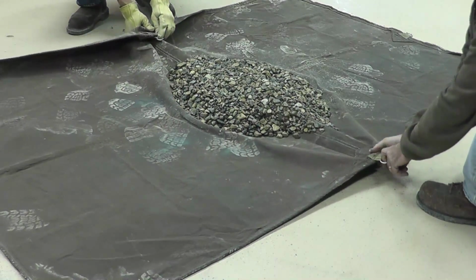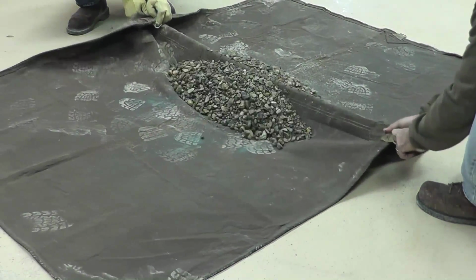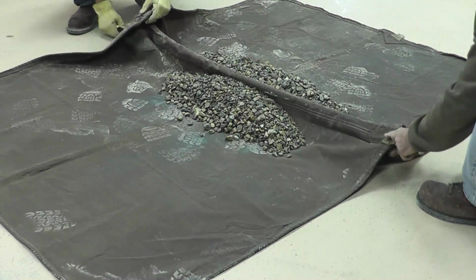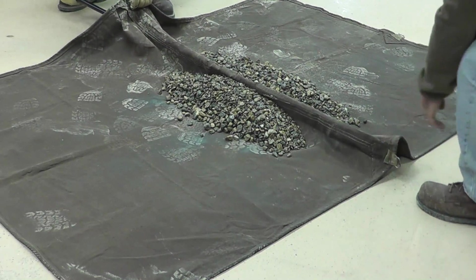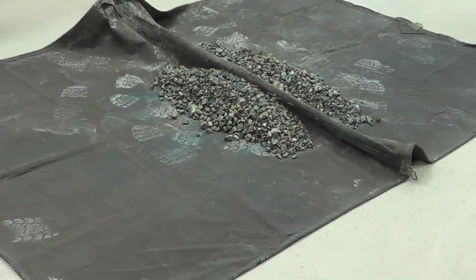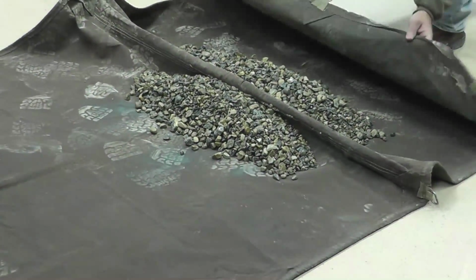Flatten and divide the pile as described in method B, or if the surface beneath the blanket is too uneven, insert a stick or pipe dividing the pile into 2 equal parts. Remove the stick, leaving a fold in the canvas between the sample halves.